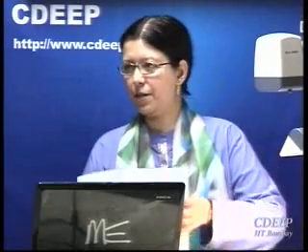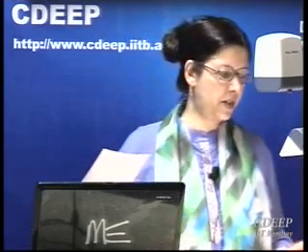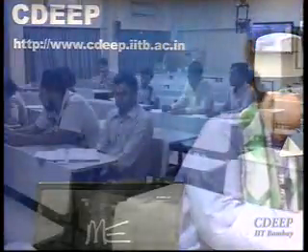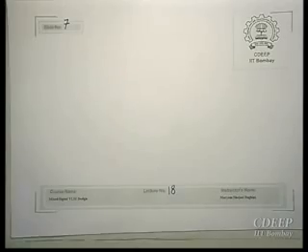And of course, to make it so, you need to reduce frequency again. You cannot keep the frequency the same as in this scheme, but it is still good enough, because by operating it at lower technology nodes, you will be able to achieve better speed. Of course, your inaccuracy problems also will be more, but overall, you will be able to get a good speed. Hundreds of kilosamples per second is a good number for many applications. Even with a good design it is possible to bring it to megasamples per second, which is quite good enough.